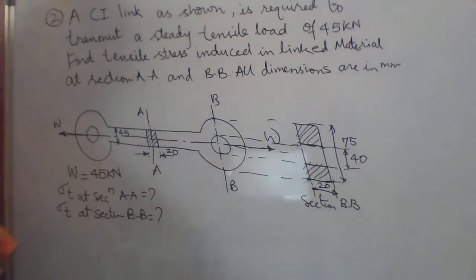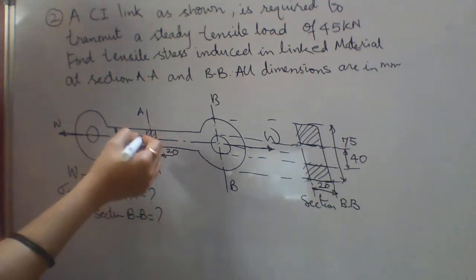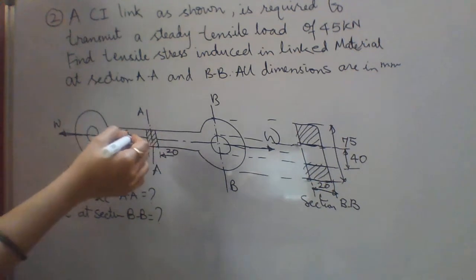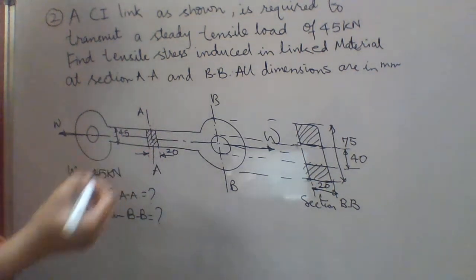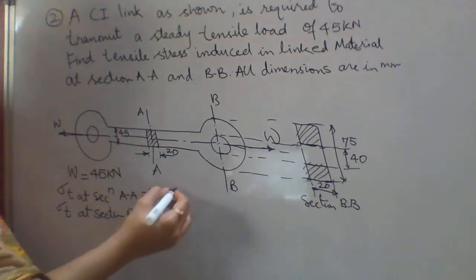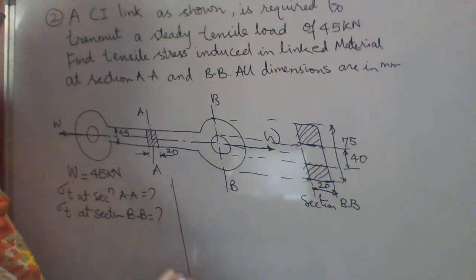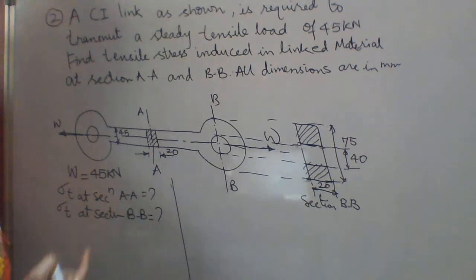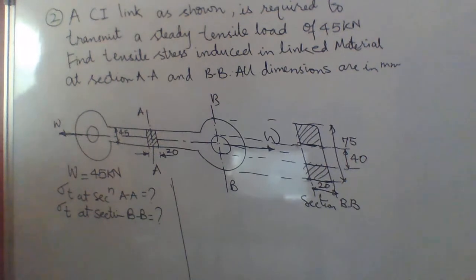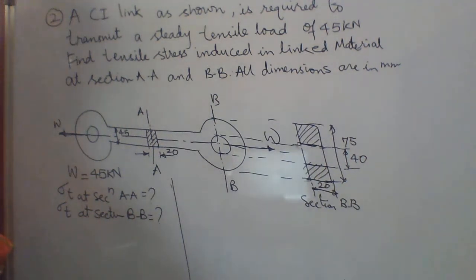Now we know that the tensile stress is nothing but the load upon area. At whatever particular section you are calculating, we have to put the area of that section only. So we'll calculate first the tensile stress at section A.